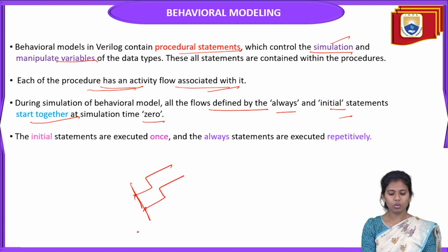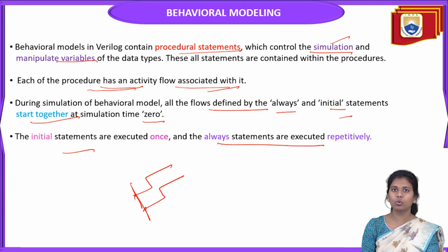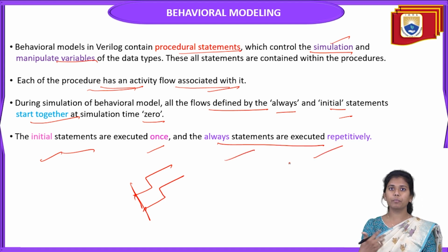Also, the initial statements are executed once, whereas the always statements are executed repeatedly. So when you compare these two primitive constructs, the important thing to remember is that initial statements execute once, whereas always statements execute repeatedly. This is one of the important points.